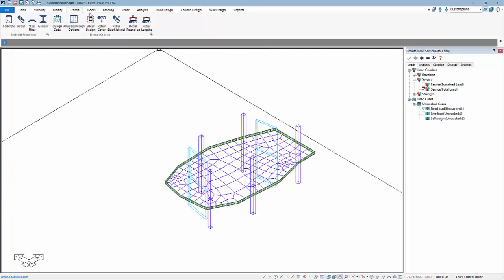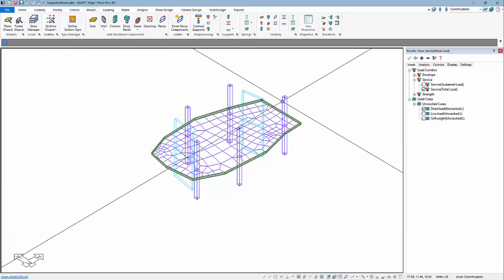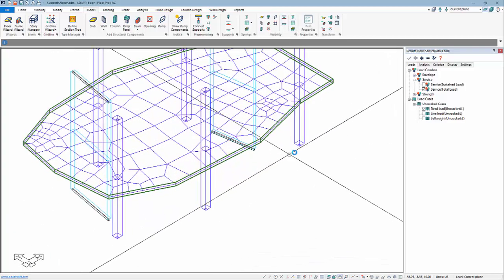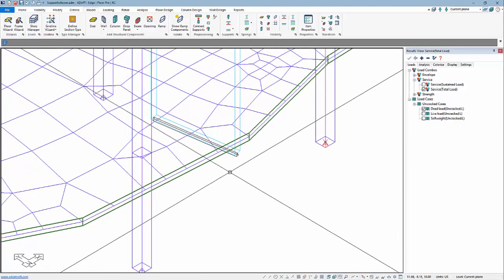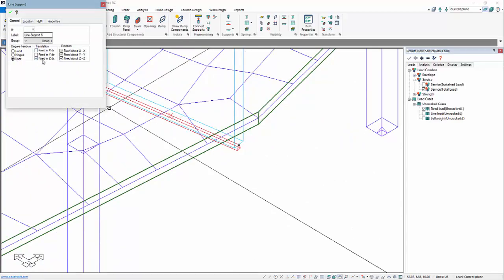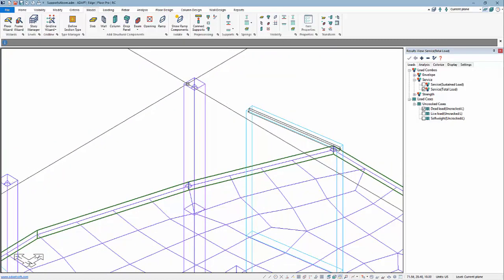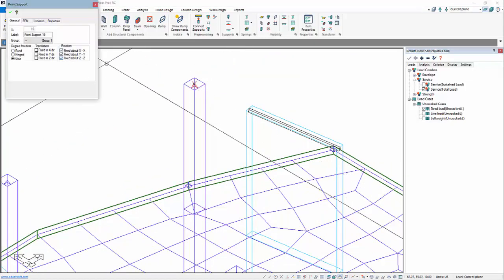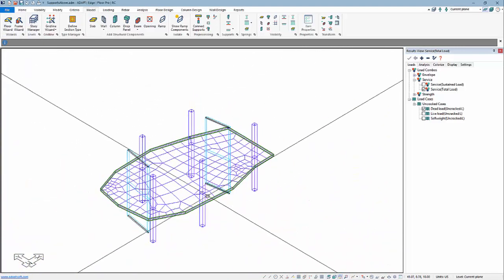And if we go to the view of those supports, if we go to model or even under visibility view settings, we can check to see what those supports are. So if I turn on the visibility for point and line supports, we can see at the base of the structure, this is going to be a fixed roller for any column or wall below the reference plane. So this is fixed vertically. If we go to the top above the reference plane, then we get this rotationally fixed only. There's no vertical restraint, otherwise this would become a hanger. And so these are the automatic supports.